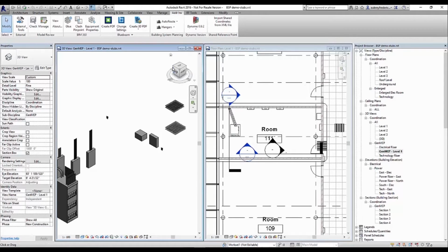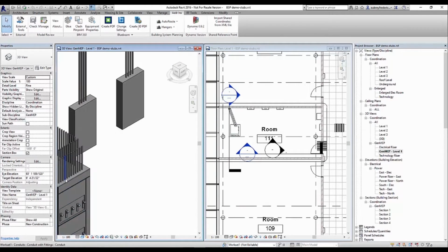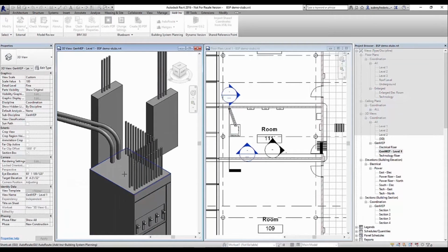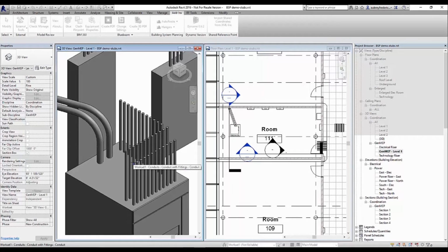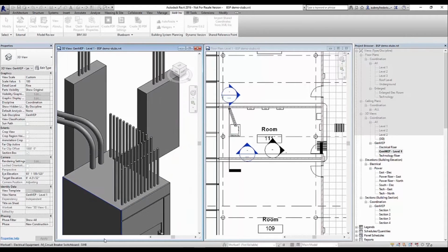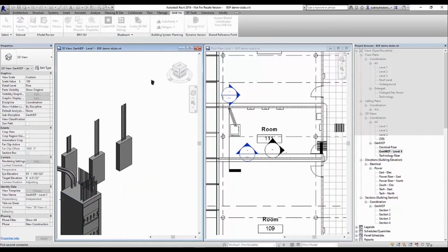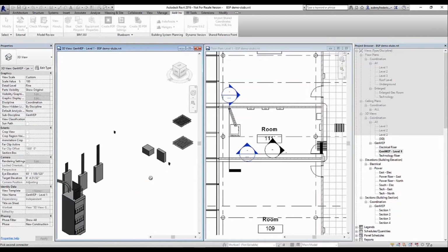I've created some shortcuts for my plugins already. So for my add-in, I'm going to use the GUI auto route, and I'll show you some of these other features as I go while I can. When I engage the GUI auto route, if I hover in space here, it should be asking to select first and second connector.